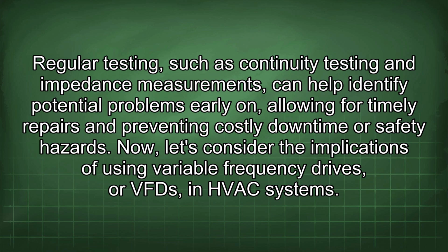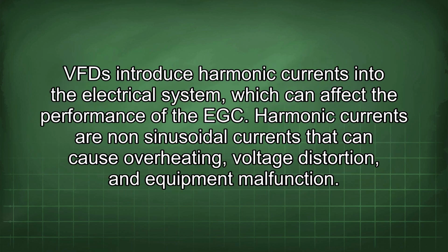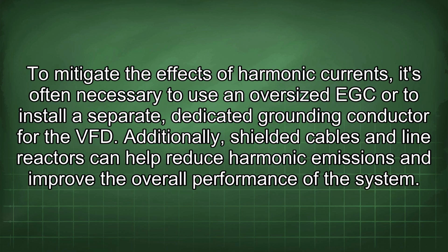Now, let's consider the implications of using variable frequency drives, or VFDs, in HVAC systems. VFDs introduce harmonic currents into the electrical system, which can affect the performance of the EGC. Harmonic currents are non-sinusoidal currents that can cause overheating, voltage distortion, and equipment malfunction. To mitigate the effects of harmonic currents, it's often necessary to use an oversized EGC or to install a separate, dedicated grounding conductor for the VFD.